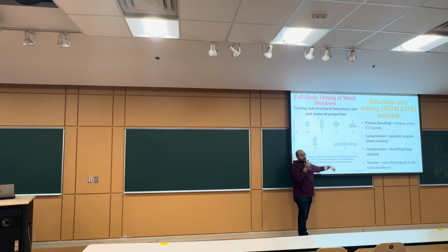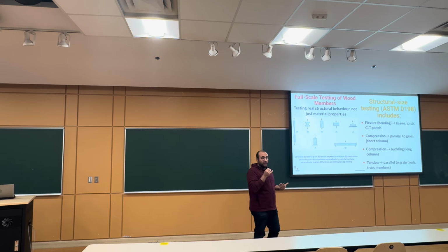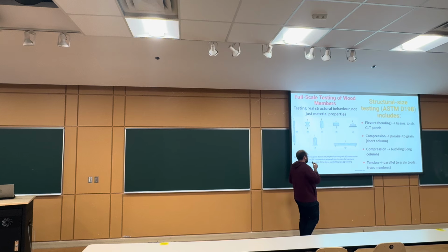In both of them we are applying the hardness test, and as we said before, we expect this one to be a bit less hard than that one, because it's perpendicular to the grain direction. So we expect splitting, and we expect hardness to be much lower in the perpendicular direction.